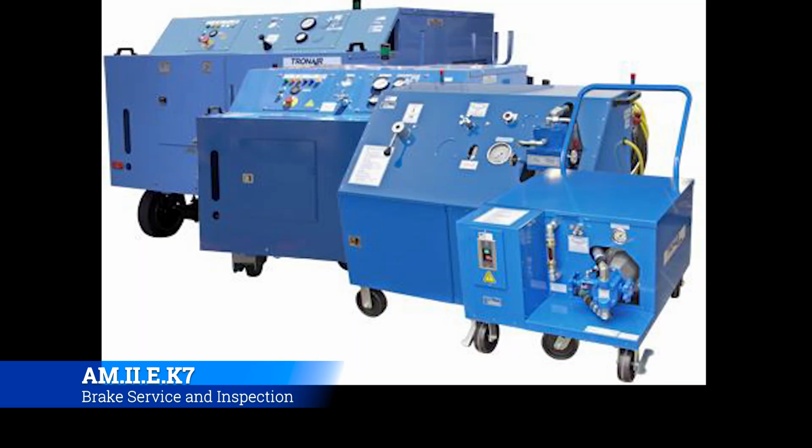Okay, so now if we decide we're going to bleed the brakes on, say, a 737 or anything that has a power brake system, you're going to end up having to use a mule. You can't bleed them out by pressurizing from the top. What you'll do is simply attach the mule to the aircraft, start working the hydraulics, and you'll effectively crack the line farther down to let all the air escape, and then once you start seeing a production of hydraulic fluid, you'll close it off.